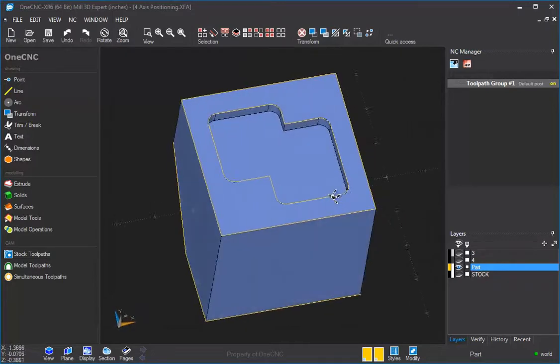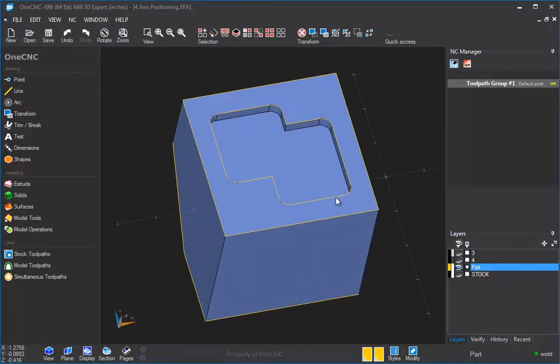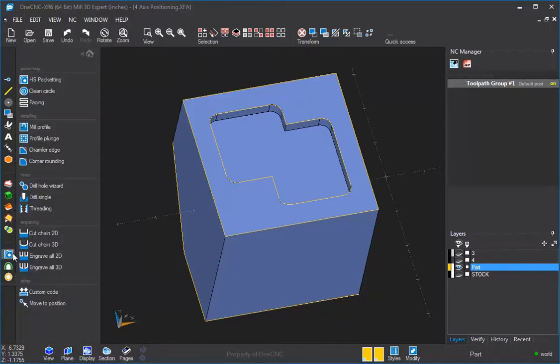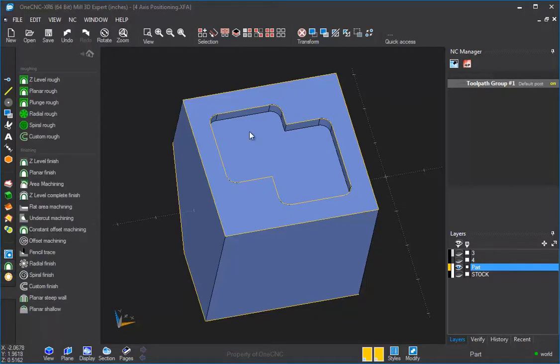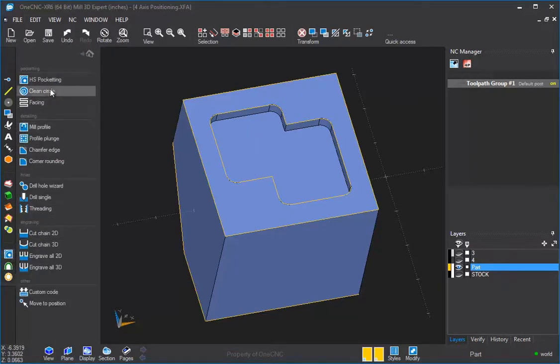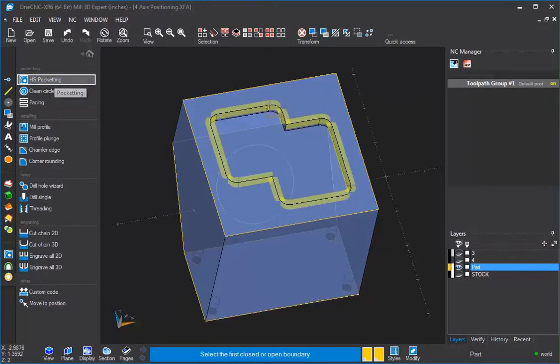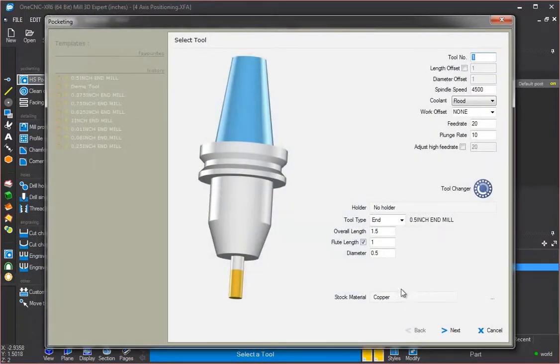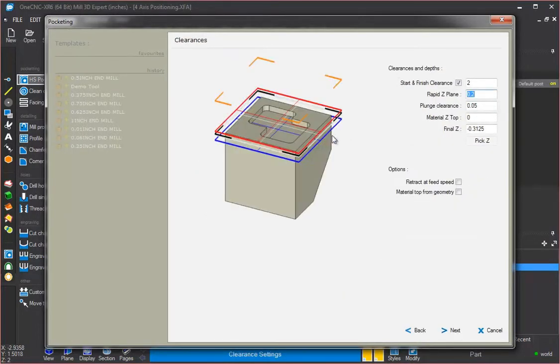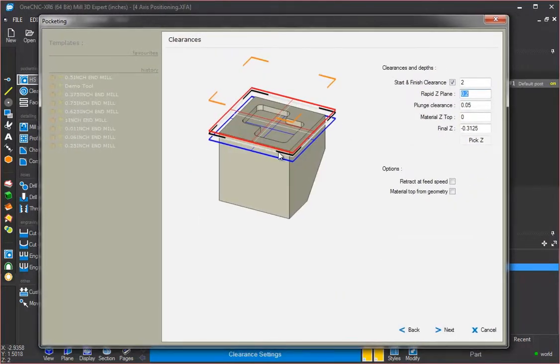That looks very good. So now it's just a matter of machining the part. Let's head over here to our stock toolpaths. By the way, I'm using 2.5 axis machining, but you could use 3 axis. You could perform surface work if you want to. But in this example, it's just 2 axis machining that we need here. So I'm going to select that pocket. I already have a 1/2 inch diameter end mill. I'm going to blast through this a little bit quick because these are things you've probably already seen before. But here is something that might be a little different.